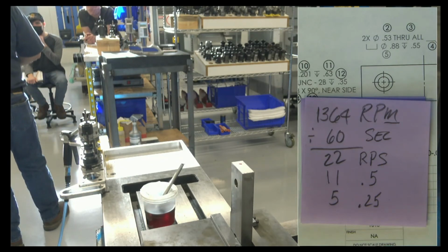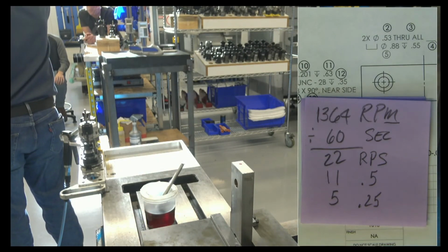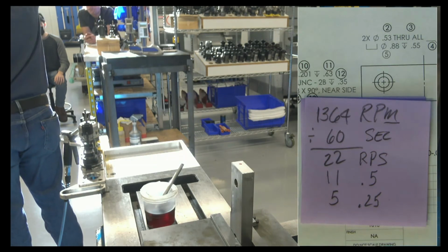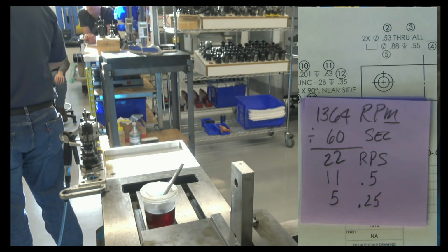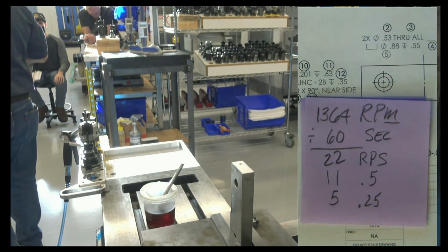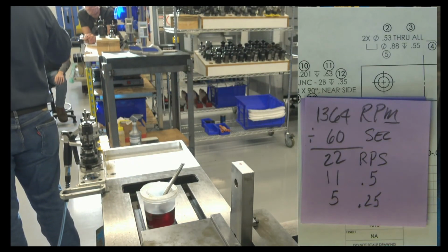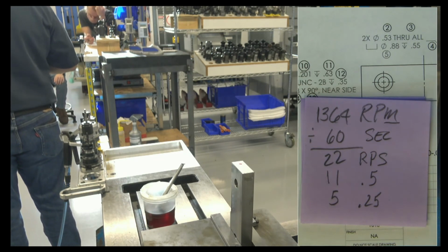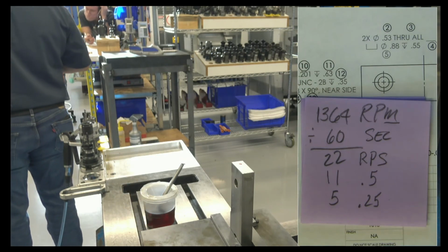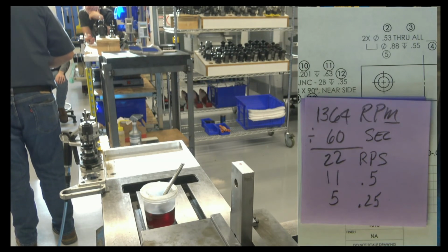So why would I need to dwell? Glad you asked that question. When you're operating a CNC machine, a drill is going to feed until it hits its Z depth, and it's going to retract. It's not even going to make one full revolution at the bottom of that feature. When we were doing through holes, that was cool. We didn't need it to. We're poking through. Here we're not. We actually want to leave that conical shape in our part. So I want to do at least one revolution at the bottom of this hole. So I need to know how long to plan the dwell in seconds.